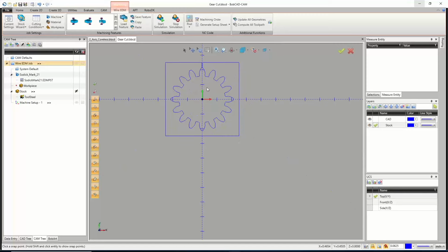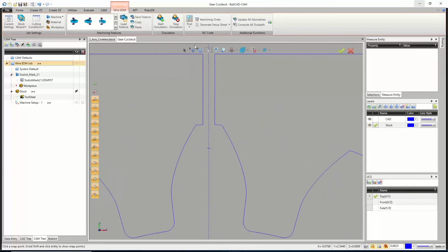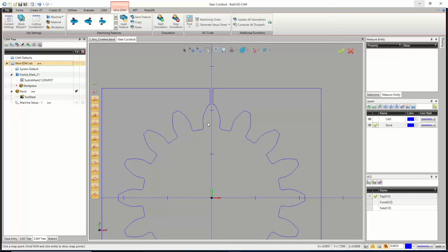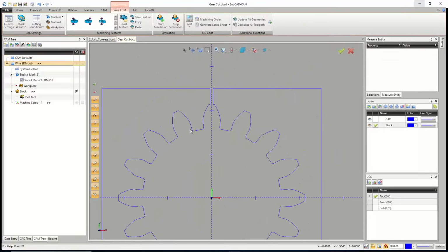So now on this part, we have a few options. Now, had I not added in this little tab right here, or the kind of this entryway in, we could have just gone and drilled a hole either wherever, on the inside or the outside. Depends on if we want to make this a punch or a die. But we could have just made a hole, and then in our case, we'd have to drill that hole, and then we'd be able to feed through that hole and make a cut, which we're going to look at with this coreless example over here.